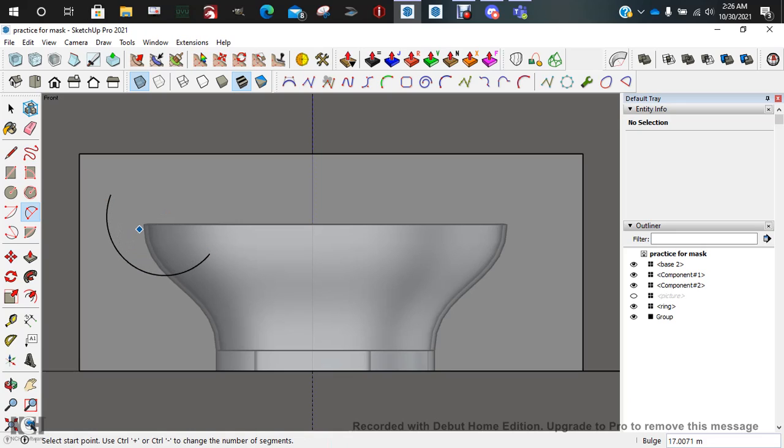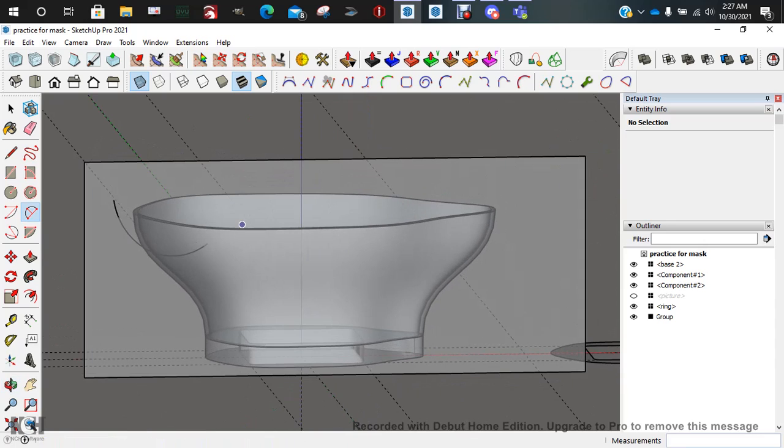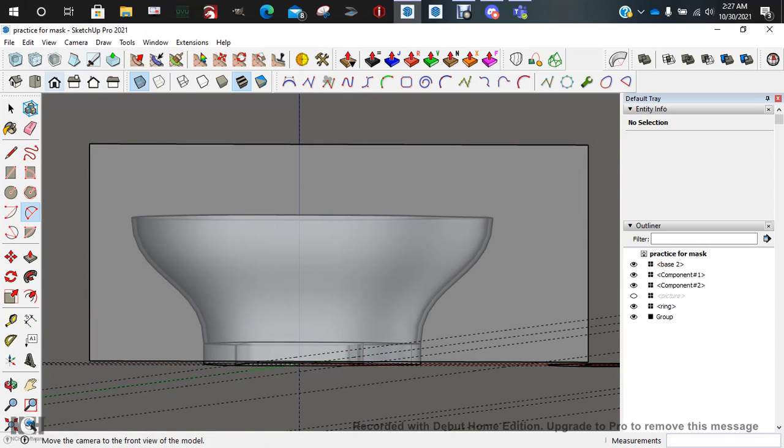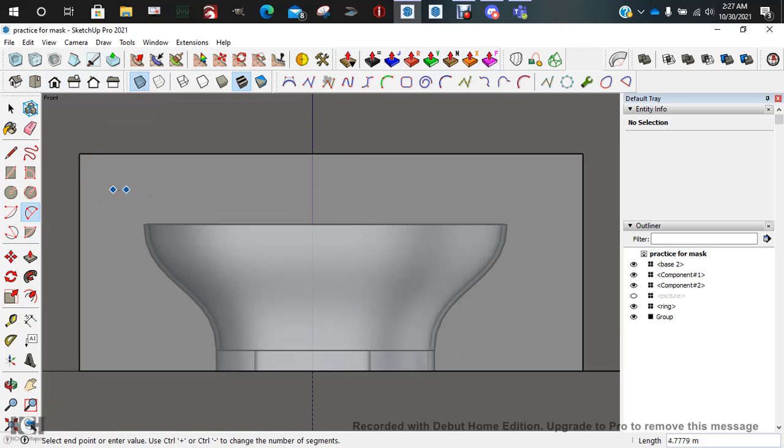along. Oh, I didn't want to click there, but what we're trying to do, I'll show you what we're trying to do. Along that face, we want about right there. And it still didn't do it. Why? See, it can get a little tricky doing this. You want to hold shift, constrain on plane. Oh yeah, you want to continue to hold shift, don't let go, till you get something like that. There we go. That's what we wanted.